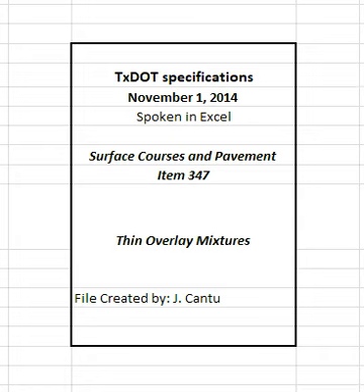Use an approved laboratory from the department's MPL to perform the Hamburg wheel test, and the department will perform the overlay test and provide results with the mixture design, or provide the laboratory mixture and request that the department perform the Hamburg wheel test and overlay test. The engineer will be allowed 10 working days to provide the contractor with Hamburg wheel test and overlay test results on the laboratory mixture design. The engineer will provide the mixture design when shown on the plans. The contractor may submit a new mixture design at any time during the project.